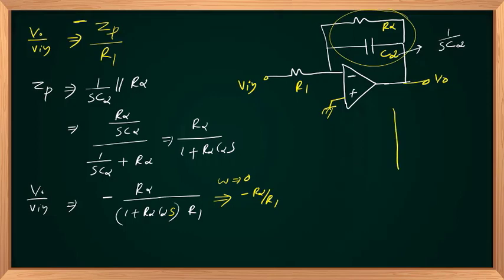So compared to earlier cases, at omega equal to 0 we were unable to mark the y value, as the transfer function was very high, saturated. Here, even though the capacitor is open circuited, the feedback is not open; there exists a resistive path. So minus R2 by R1 is the voltage gain.